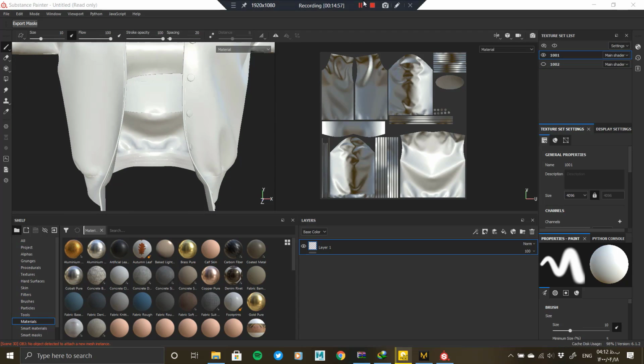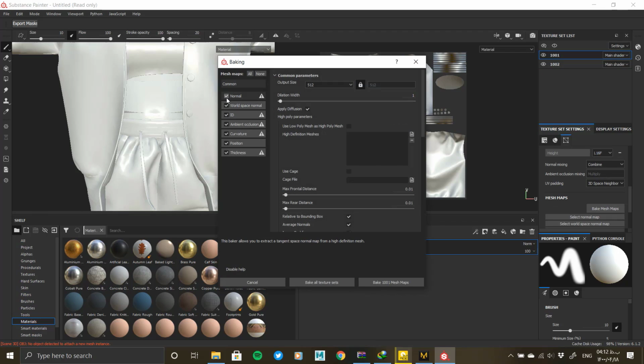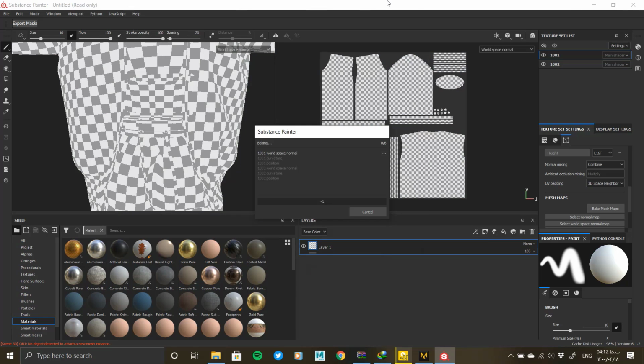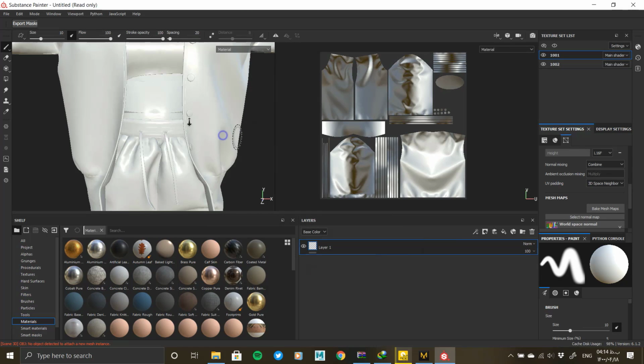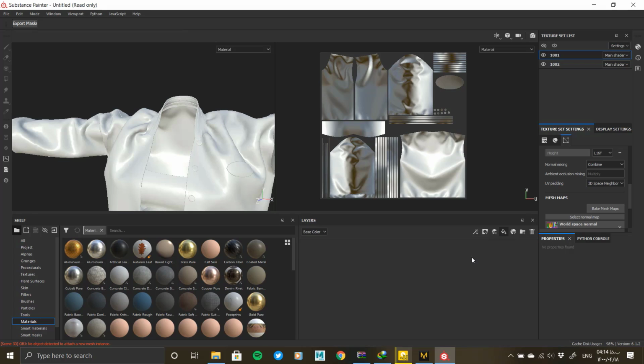If we have a model without thickness, it is better to change the type of shader, so that the normals appear on both sides of our screen. Now we see in which of the poly groups we specified, it is applied as a texture list. Now it is time to bake the high poly model on the low poly model. In the baking section, we define the high poly model of the selected section, and we bake the normal, AO, curvature, etc. maps as needed. Pay attention to the size of the bake maps, and not all of them need to be in their largest size.